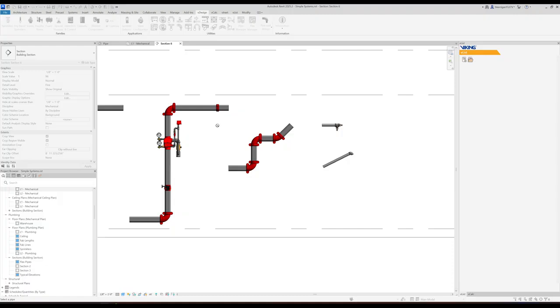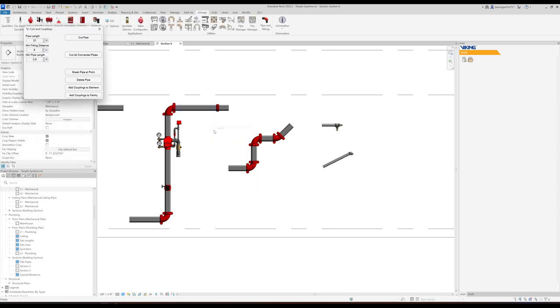If you're using a pipe type that uses flanges to represent the grooved couplings, this is a pretty helpful command because the stock Revit break pipe command will just insert a back-to-back flange, so you'd end up double counting couplings if you're using the Revit schedules, whereas this command will temporarily disable that routing preference and you would only end up with one actual coupling.